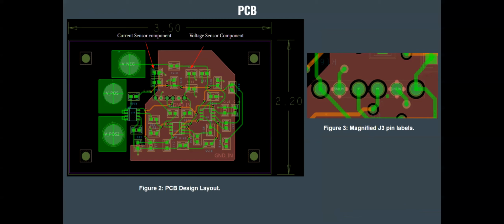One of the key concepts of the board layout is the isolation and the attempt to avoid trace overlapping related to the current and voltage sensor connections. The 6-pin junction was placed at the center since all the subsystems and components lead to that junction. The capacitors connected to the sources on the ICs were also placed beside the corresponding ICs.